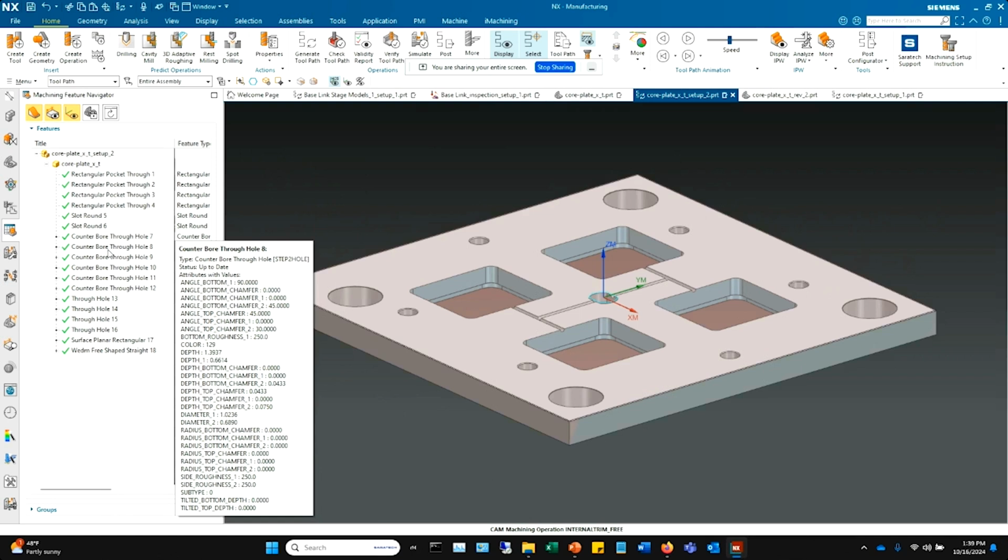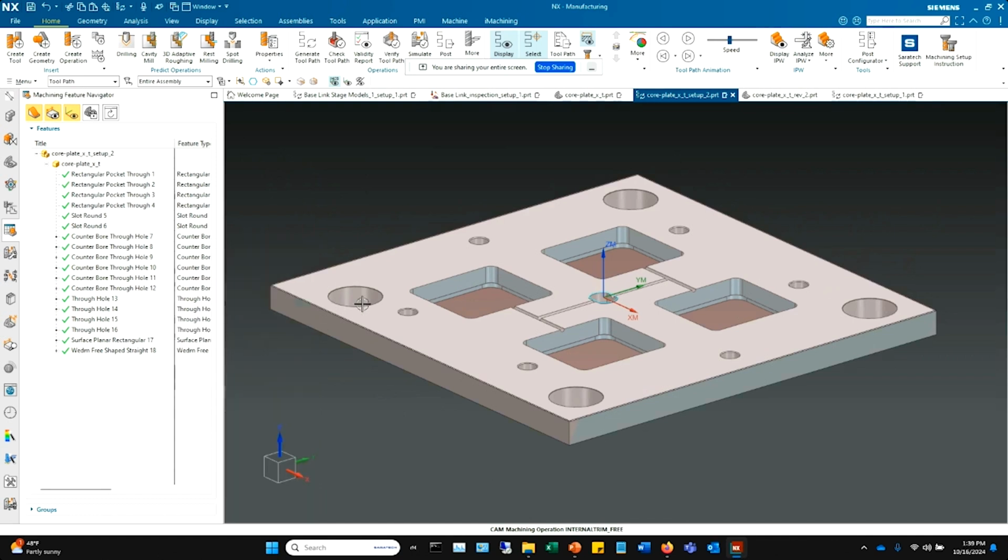So this is how we get this automation to run, how we get those libraries to function. I could tell it that this particular hole, by simply putting a PMI symbol of a 10 finish on that, may pull an insert drill, and this one may pull a 7 tool operation set to get a fine finish. So by minimal work, we teach the software what things are, and then it interrogates it later and auto processes what we have done previously, so that when we develop toolpaths, we know that they are the most sophisticated toolpaths out there.